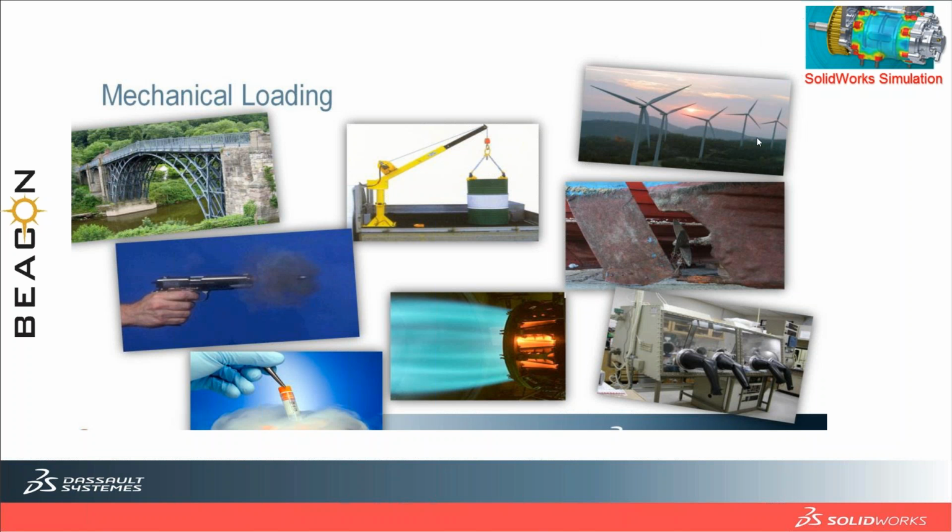And you can see here some loadings. It may be thermal loading also, whenever you have a range of temperatures varying from cryogenic to room temperature, that is also considered as one cycle. So it may also lead to fatigue failure.